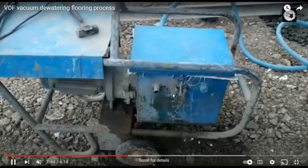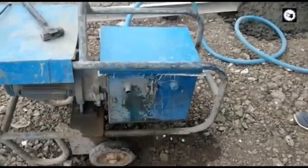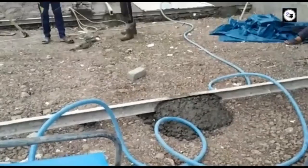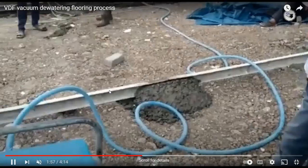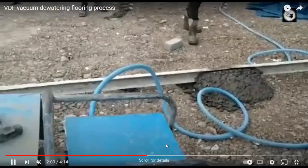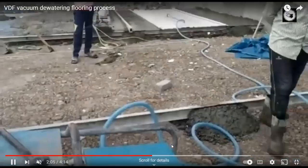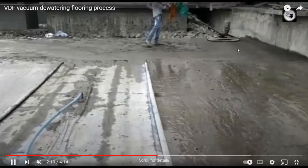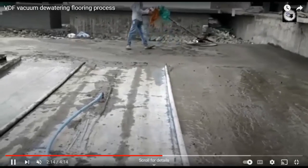So the dewatering process takes approximately 1.5 to 2 minutes per centimeter thickness of your slab. The process is very fast when compared to other manual concrete flooring. After dewatering, the floater machine is used to trowel it. Troweling is nothing but the finishing of concrete.